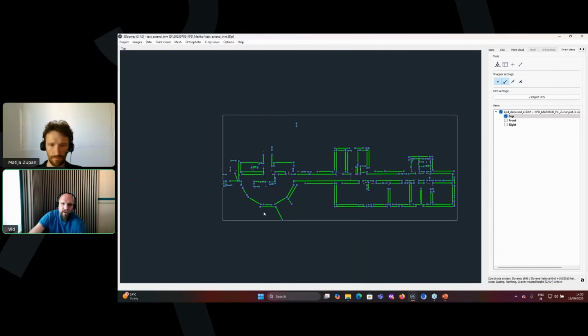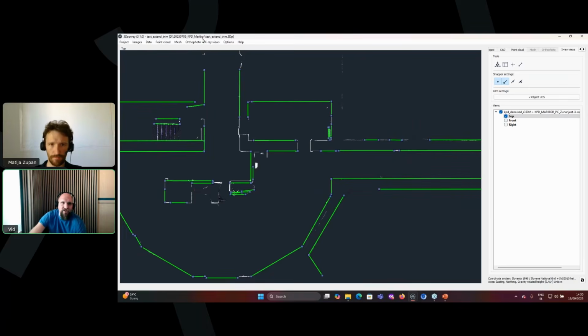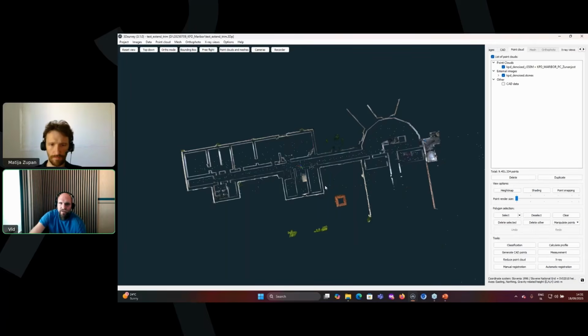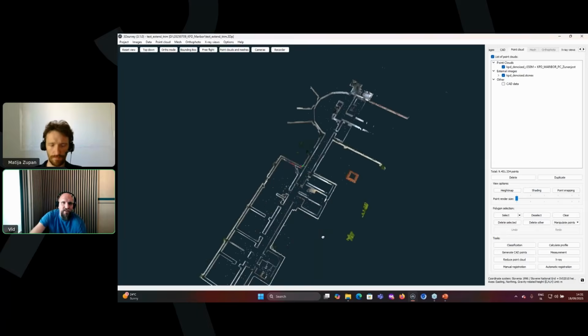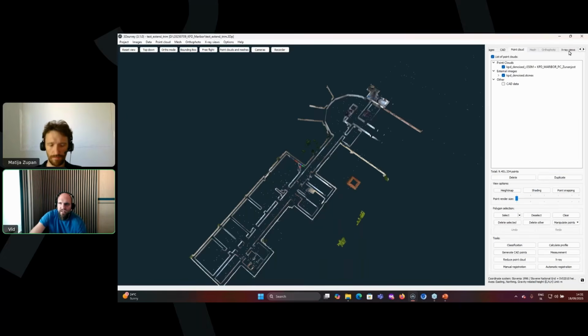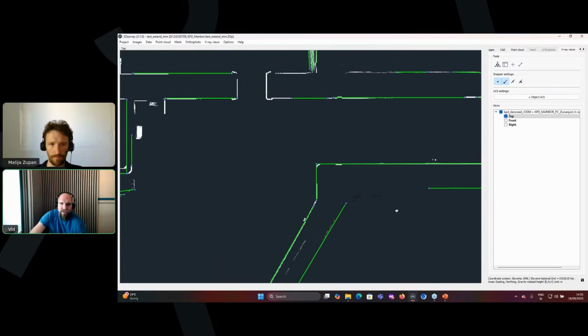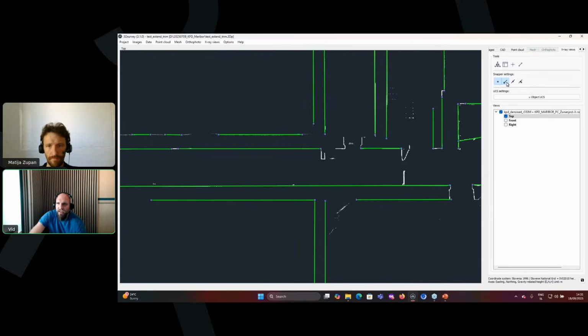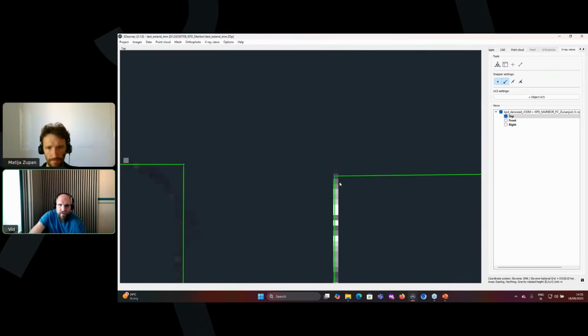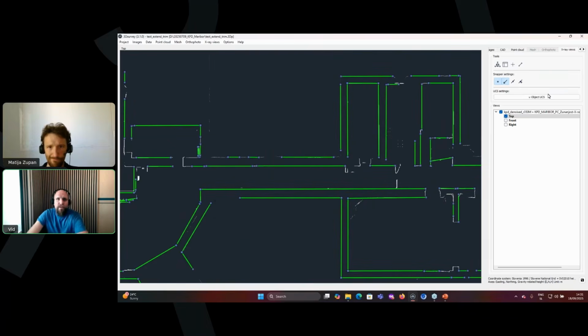One way to achieve that extraction could be to create an X-ray in 3D survey. These were the functions that we were showing earlier. You go into the point cloud. Here we made the section directly in the point cloud, and then you would go to X-ray view and calculate new X-ray views. In that case, you get these top-down views. Then you can enable point snapping and improve on the design like that, because here we would go into automatic line detection. This would give us these kinds of lines, and then we need to improve on them.